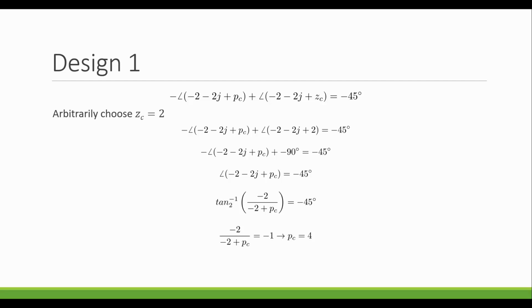So with the 0 chosen and the pole chosen, I can put together my G' or my GRL, and this is what I want to put into my root locus equation. So now the top from that 0, I have an s plus 2, and then I have an s plus 4 on the bottom. Now, it turns out that in this case, by choosing a 0 in my controller to be equal to 2, one of my open loop poles from the plant cancels with it.